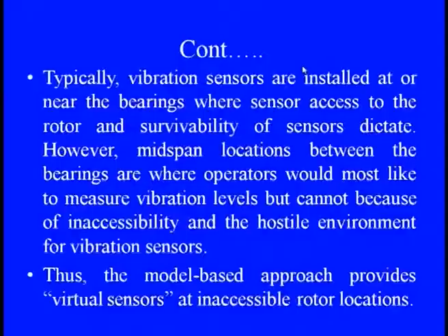When we are talking about the installation, you see where the vibration sensor is to be installed. They are generally installed near the bearings, where you see the accelerometer or any of these probes being installed. Or else we can say that wherever you see these kinds of rotating devices, whatever the closest positions are, we can install those things.